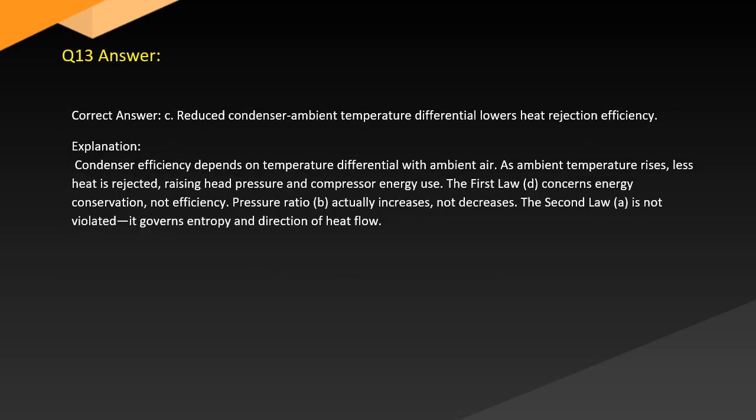Answer. Correct answer: C. Reduced condenser-ambient temperature differential lowers heat rejection efficiency. Explanation. Condenser efficiency depends on temperature differential with ambient air. As ambient temperature rises, less heat is rejected, raising head pressure and compressor energy use.